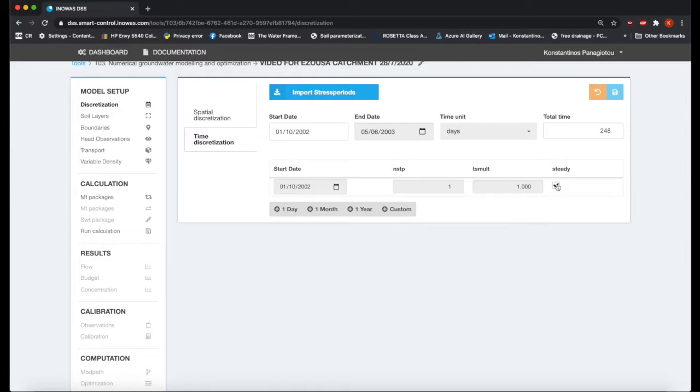But in our case, since we are considering a number of stress periods, our simulation evolves in time until it reaches eventually the steady period. This is also more stable in terms of computational stability, so we prefer to do it like this. So in our case, we are going to consider transient computations, which eventually reach, after a sufficient period of time, the steady state solution.